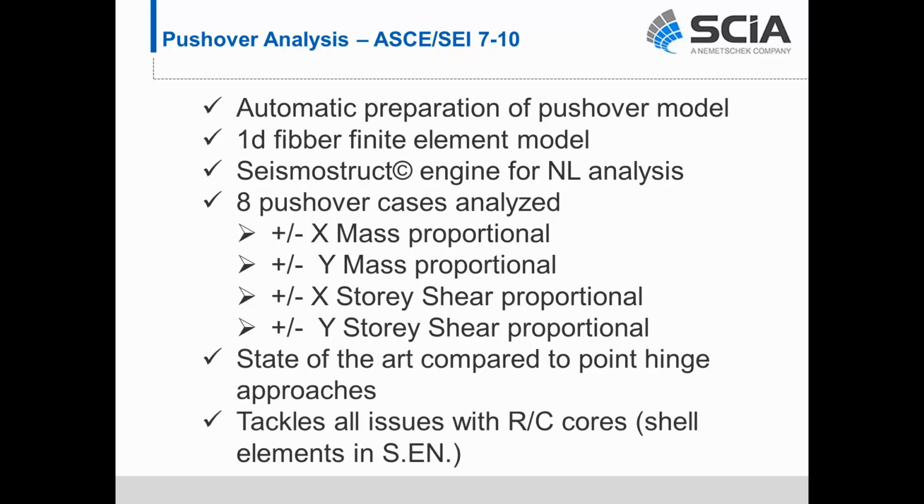It does automatically 8 pushover cases, 4 mass proportional and 4 story shear proportional. And have in mind that because it's not a point hinge approach but a fiber element approach, it tackles all issues with RC cores, which you cannot tackle when you have point hinge approaches.